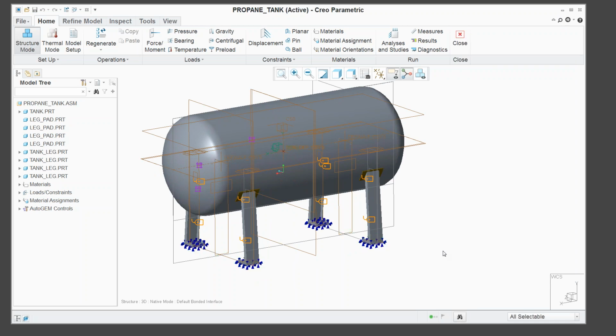There's quite a library of loads and constraints you can use. One of them, by the way, is symmetry. We could have sliced this model in half, possibly, or in quarters, but that precludes doing mode analysis later for vibration, and that actually does limit you. You could make the model both ways, I suppose, too.